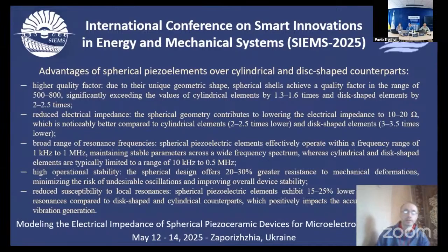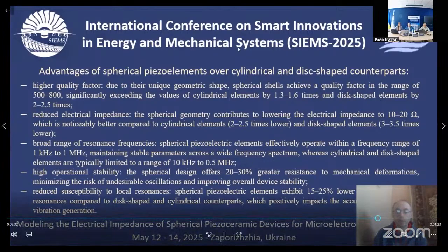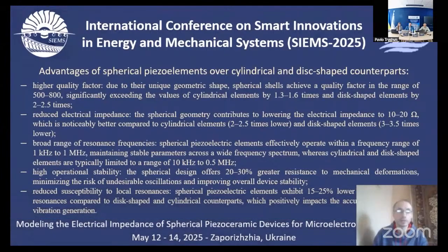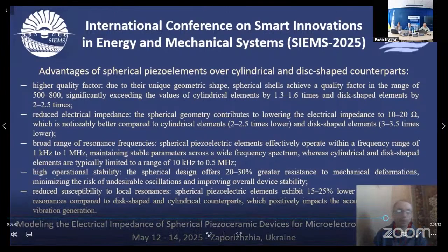Thus, it was found that spherical piezoceramic shells have a number of advantages over cylindrical and disc analogs, which makes them promising for use in microelectronics, diagnostic, and sensor systems. In particular, they demonstrate a higher quality factor, lower electrical impedance, a wider operating frequency range, increased stability to strain, and lower sensitivity to local resonance, which improve the accuracy and quality of oscillation generation.